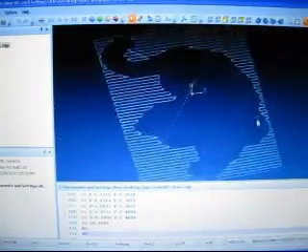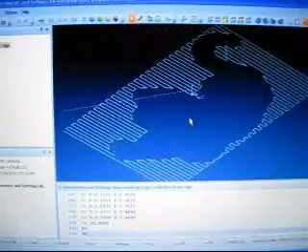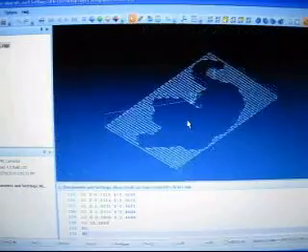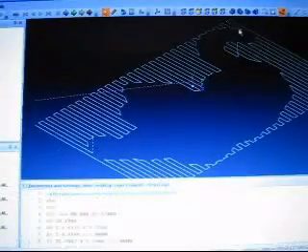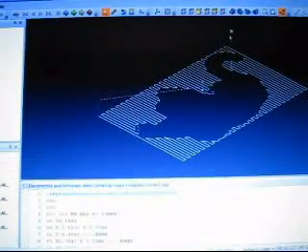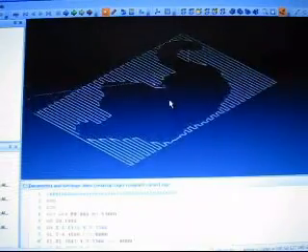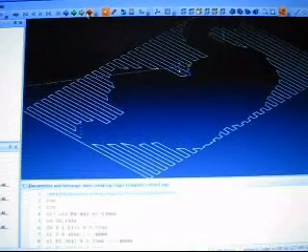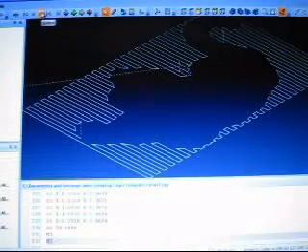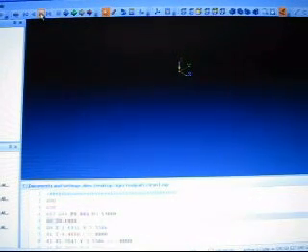So what's our next move with this thing? Here's what we need to do. We need to add a ramping operation to this because, as you know, we're not using a center cutting bit. I'm just going to rewind the program and show you what it does. First, we're going to jump up to our clearance and then we're going to wrap it over.